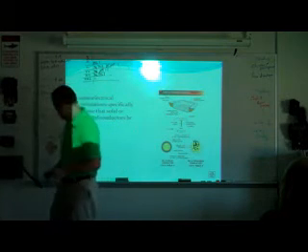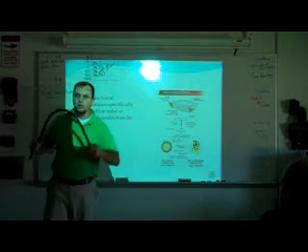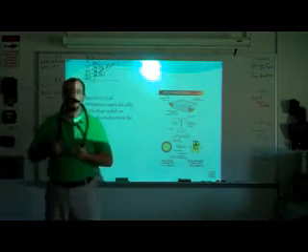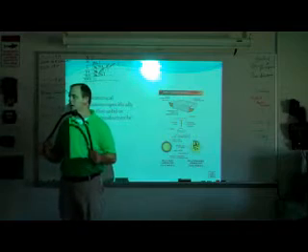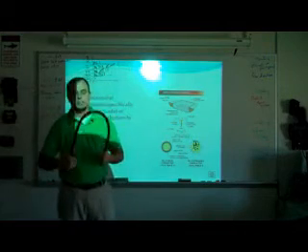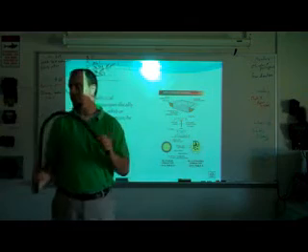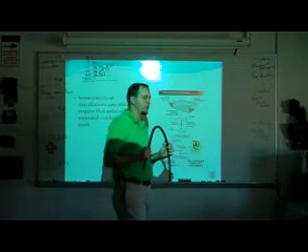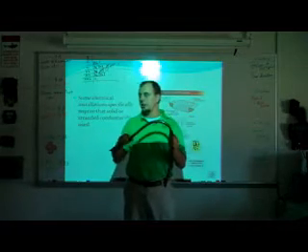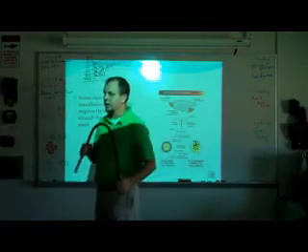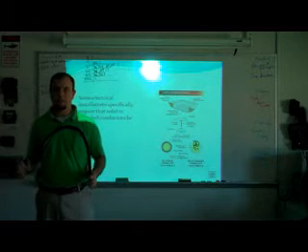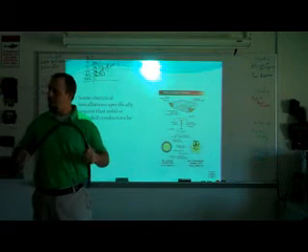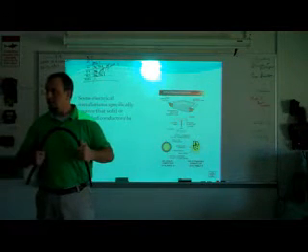Once you get above 8 gauge, then you go to stranded. Why would I go to stranded? Flexibility, right? If you're in the morning class, you know all about flexibility with our stranded wire. It just kind of flops everywhere. Our nice Romex, we can bend it, make it look real pretty. With that stranded, you try to make it look pretty and it just coils back up. That's the flexibility of it. So that's why, once you get above 8, it becomes stranded. And if you ever have to bend 8, it's a booger.